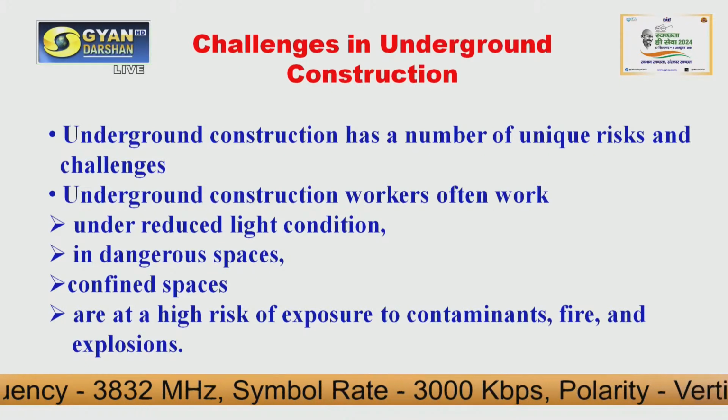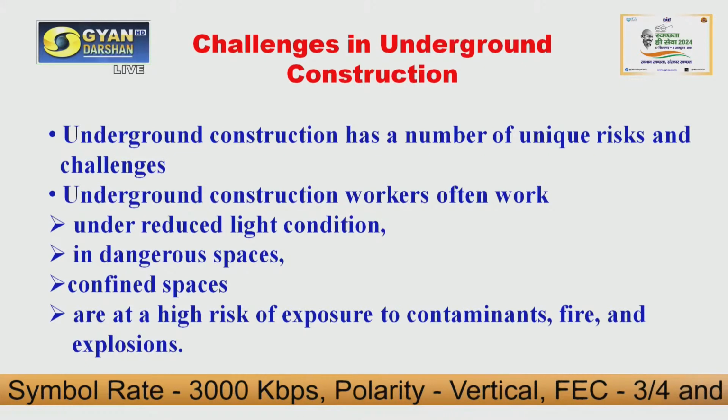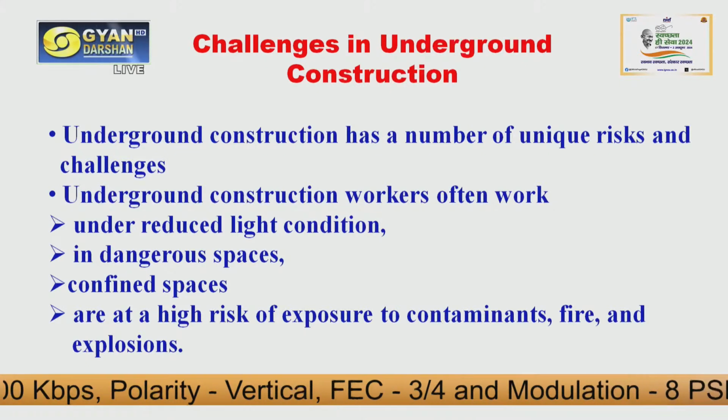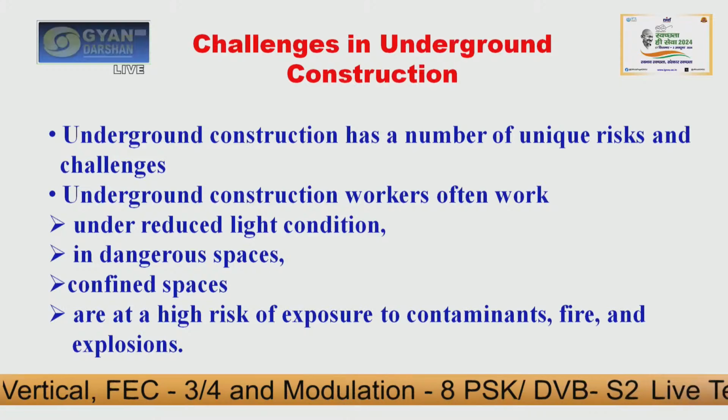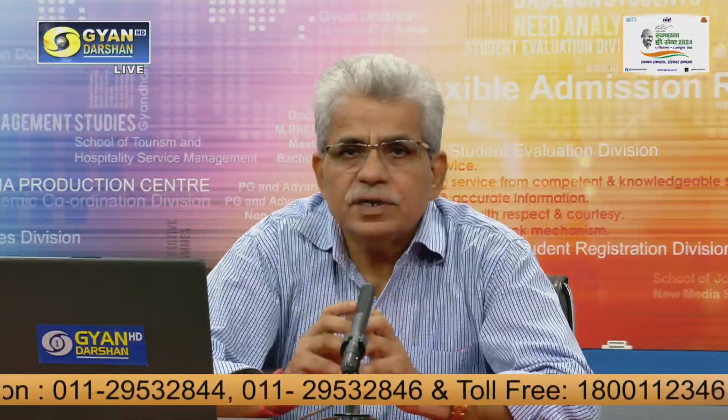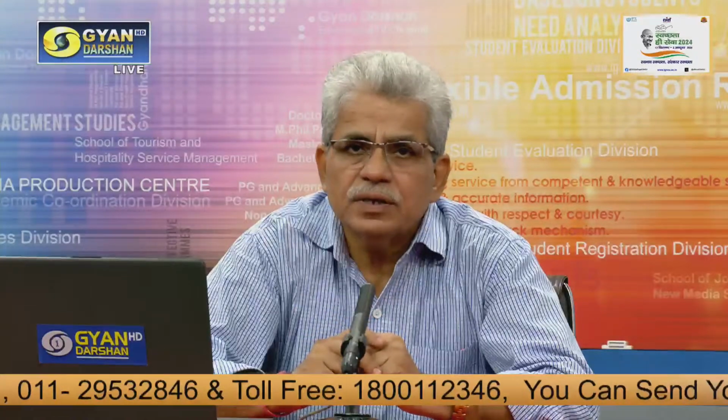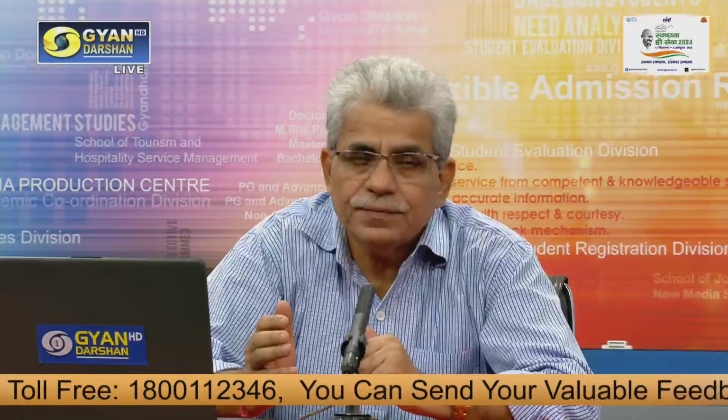First of all, the light problem. There is a limited source of light basically. When you are working at the ground, enough light is there, and visibility is up to a large distance. But when we are working underground, especially in tunnels, shafts and passageways, only artificial light is there, and you know that artificial lights have limitations, so visibility is not too far.